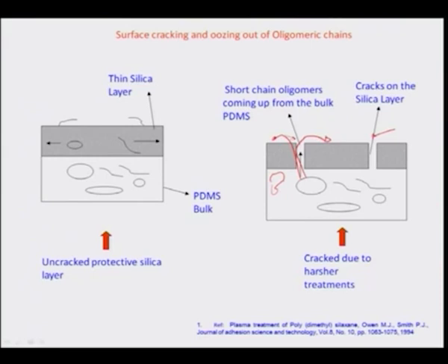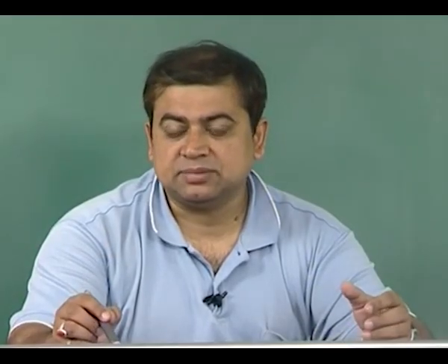So, the bonding between the surfaces is an immediate process. Whenever you have the OH groups just formed on the silica layer immediately after the oxygen plasma exposure, that is the right time for bonding between the surfaces, because if you delay or wait, there is always a tendency of the hydrophobicity to recover, and a lot of methyl groups come and crowd the surface, and that is going to ruin the bond strength. So, that is how polymeric bonding in MEMS can be realized.